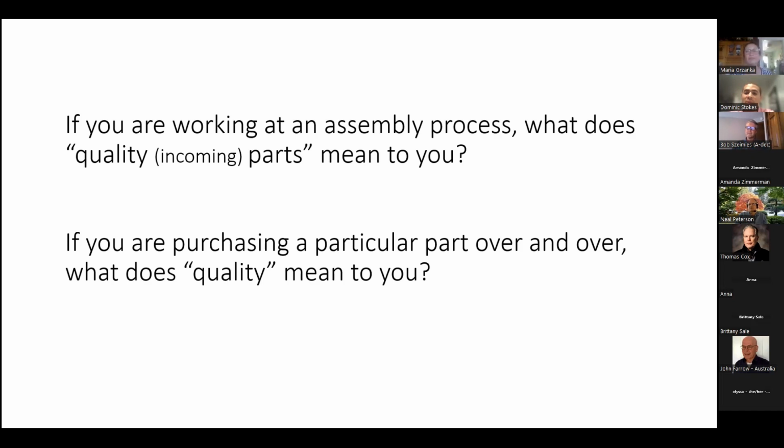Can I say something, Maria? If this were me, it's a combination of the 5S. I want those parts delivered, labeled clearly in the same place so that I know where to grab them. And I know that I'm not grabbing another shaft that kind of looks like it. So I know that I'm building the right parts, but then I need validation when I build it to know that it's good before I pass it off to the next person. Some sort of visual check, something that I write down to say, I just built this part. And not just because I put it together is it good. Something else validated that it is actually good.